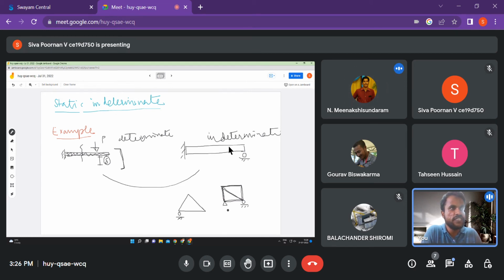So basically, it comes from the definition of static determinate, right? Static determinate means total knowns is equal to total unknowns. Every bar, we don't know the actual force, right? And that gives, if m bars are there, m unknowns. And if the reactions are also unknown, that's also unknown. And how many equilibrium equations do you get? Every joint is subjected to many forces, and we can take equilibrium equations in two directions, horizontal and vertical. So two times the number of joints is the total number of knowns. So if this happens, then we say it is determinate. No, we don't say. We could have an indication that it is determinate, right?